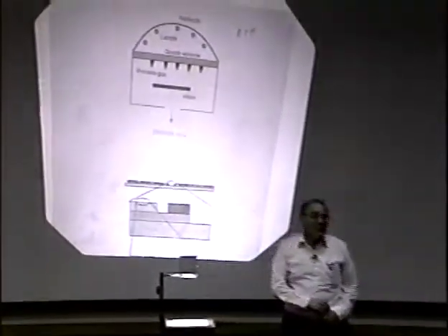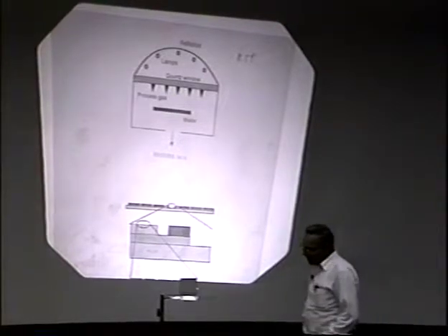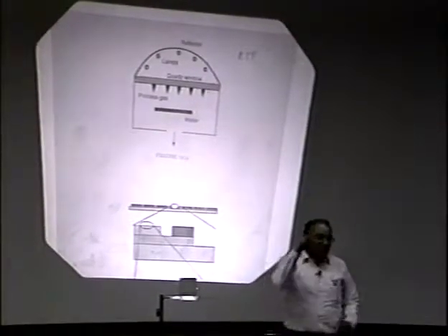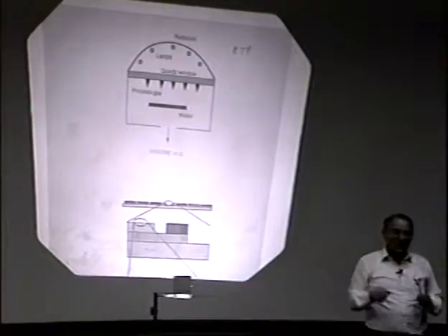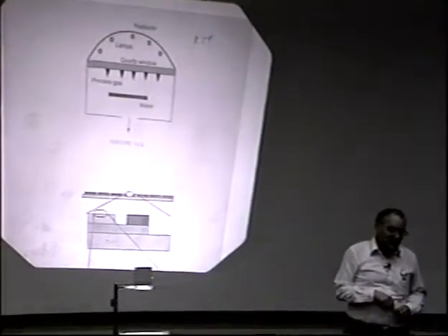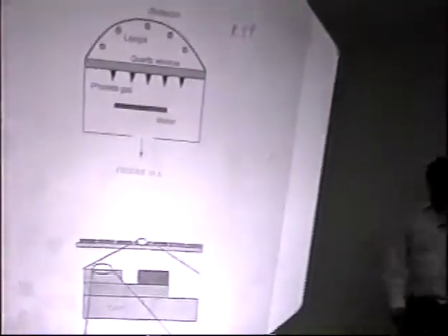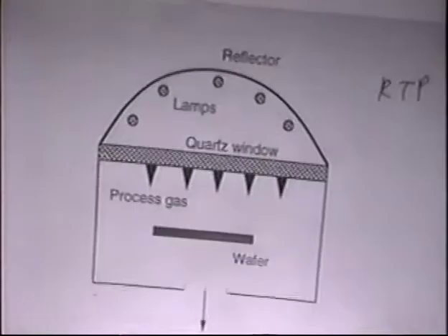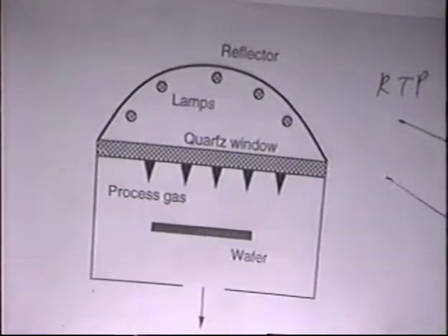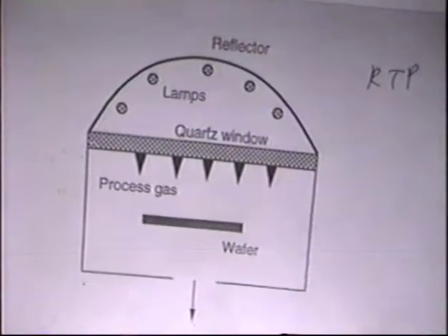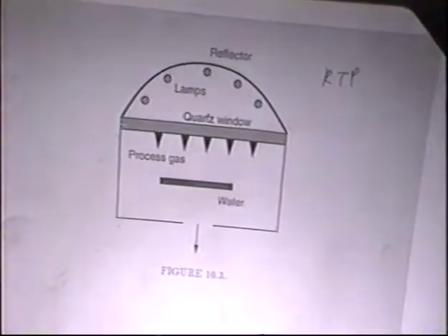This is another example of what is called rapid thermal processing. Once the vapor has landed, they want to make it stick, and they do it by baking it. They can either put it in the oven, the same way they make bread, but there are other ways to do it, which are cleaner. One of them is simply to put some lamps around and raise the temperature about 100 degrees per second for about 10 seconds. Keep it there for several seconds and then shut it off.